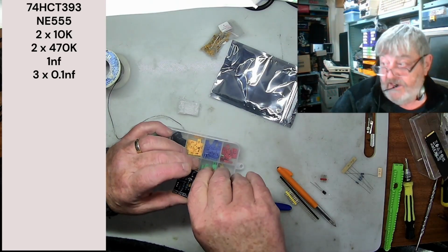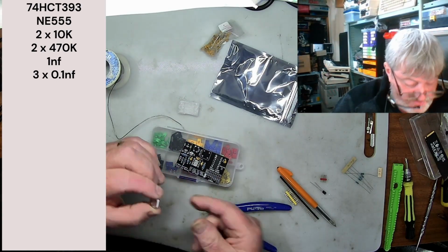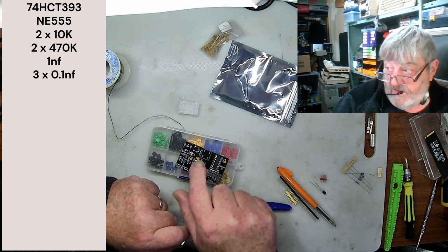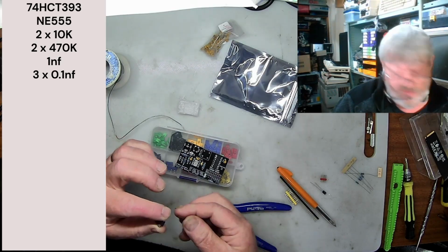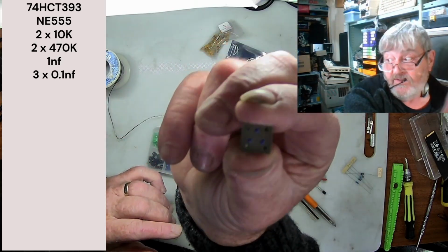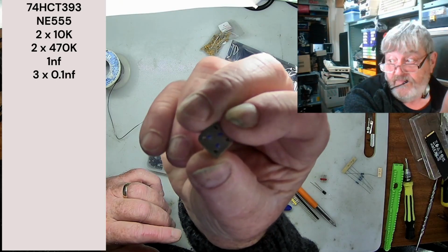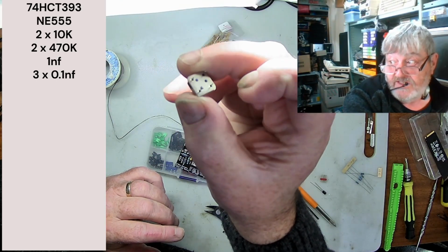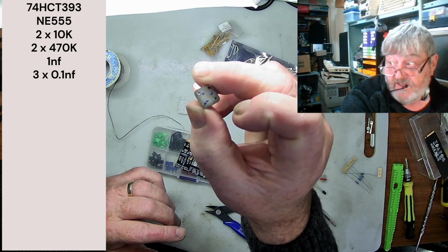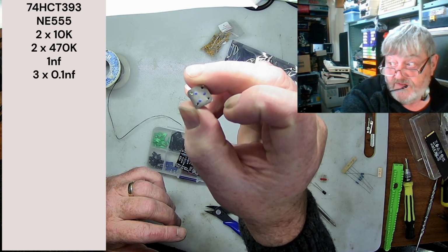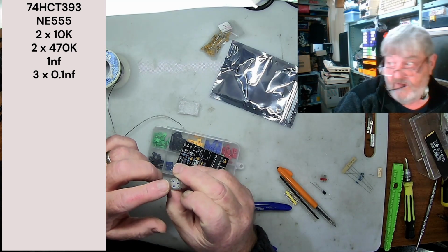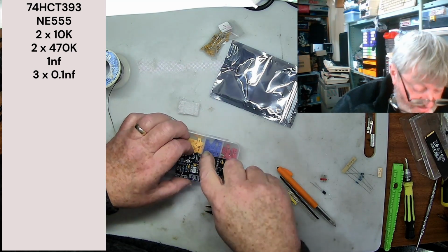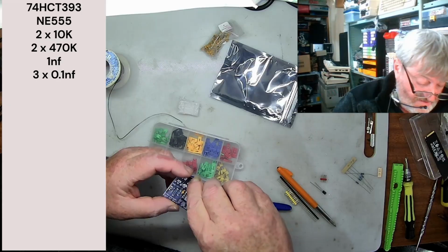So the other thing to look at on your crystal, if you're not too sure, the outline on the board has 1 square corner, and if you actually look at the chip where my thumb is, that corner is actually square, not rounded like the others. I'm not sure if you can quite see that, but that one there is actually a square corner, so that lines up with the square pad on it.